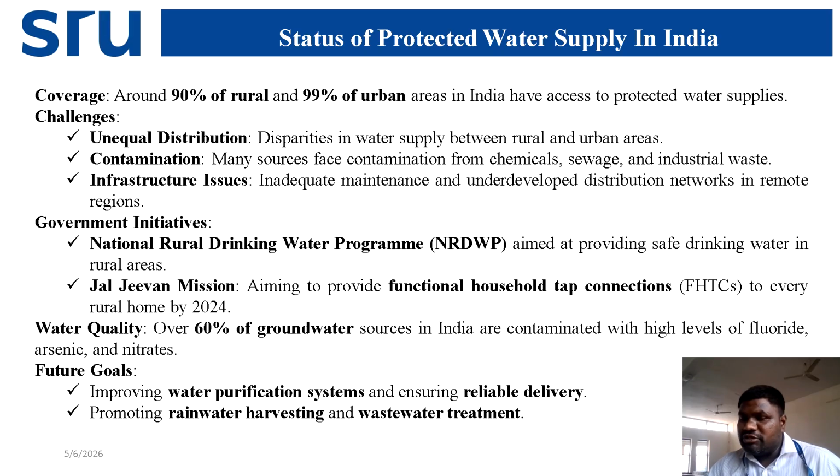Here what we have to do is provide some kind of detention time. The water is coming to the reactor, and we need to wait for a particular amount of time, maybe 15 to 20 hours, so that the impurities and the BOD are removed from these reactors.